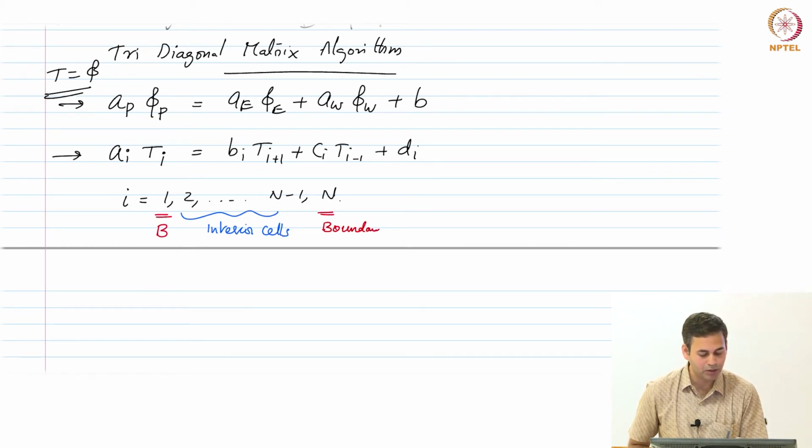Boundary cells, I mean the boundary condition itself. So, that means 2 itself is a boundary cell, because it is sharing one face with a boundary. Essentially, 1 and n is where we apply the boundary condition, and 2 to n minus 1 are the unknowns that we have to solve for. All right. So, let us say I have a Dirichlet boundary condition.